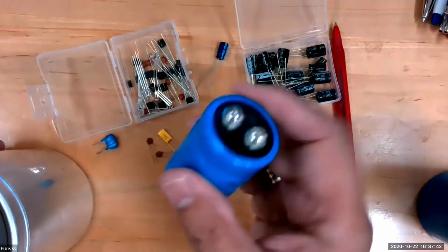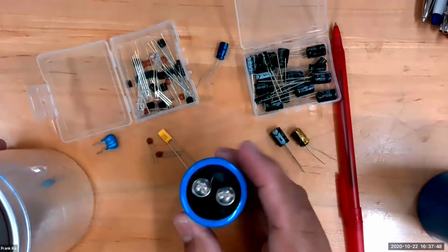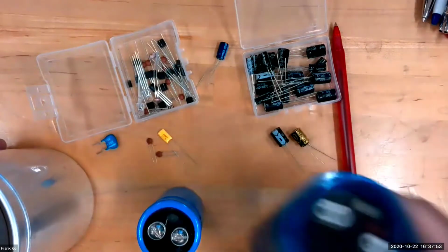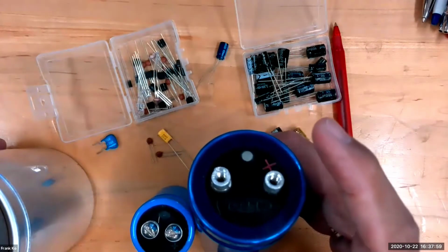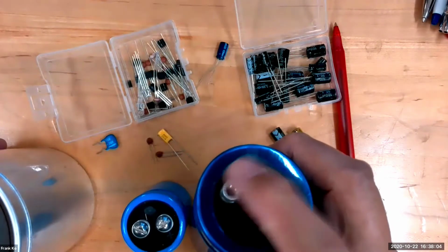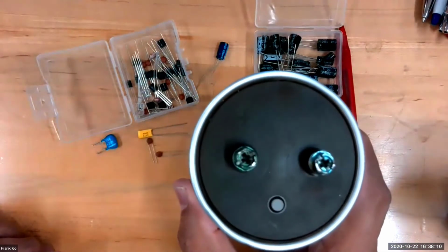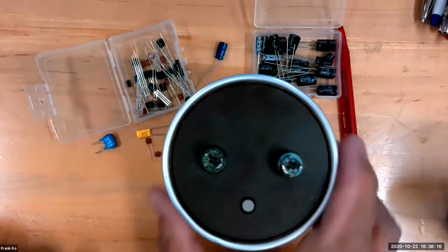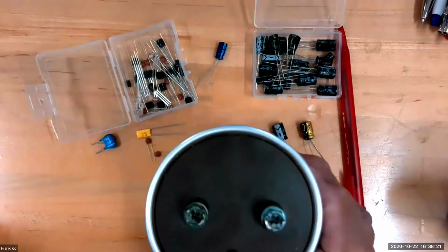So if you look at the terminals here, these screw terminals are perfect, not damaged mechanically or electronically. These are screw-on terminals. So we put bolts into these because they have so much current. These are also undamaged. Oh, this one's physically got some scratching. If you take a look at this one here, this one shows some physical damage for sure. Let me go ahead and focus on that. Yep, it's got some physical damage. And the physical damage is because I've sparked this and arced this a number of times.